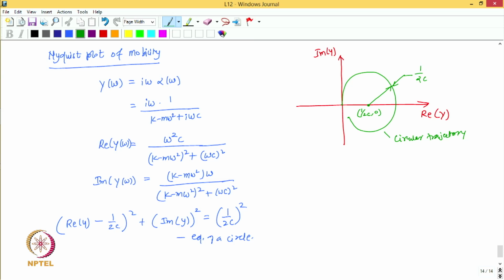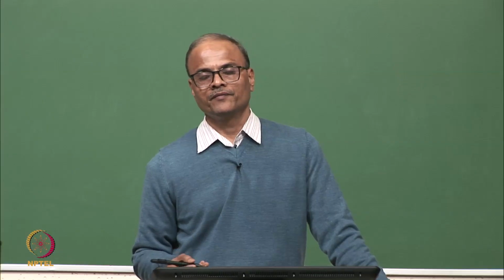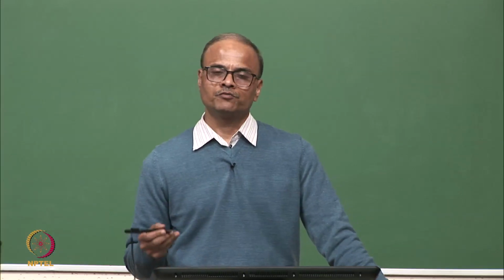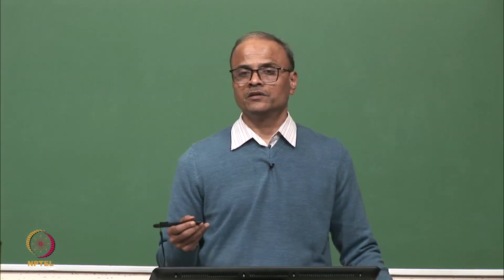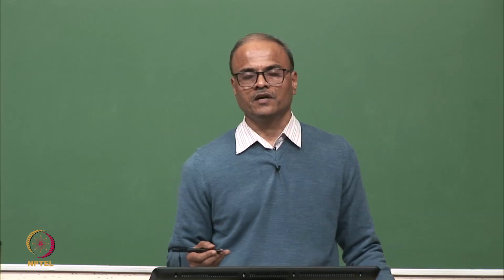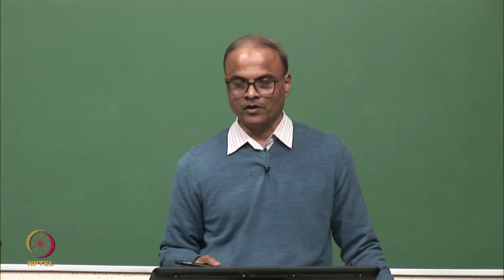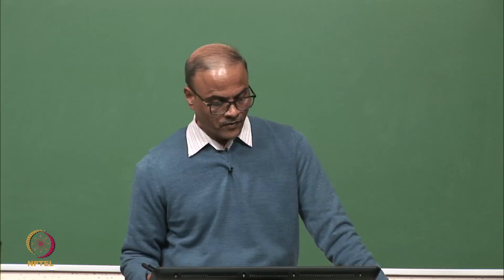This is a very important property of the Nyquist plot of mobility for a single degree of freedom system with viscous damping, and later on we will make use of this property in one of the methods of modal analysis, where we will see how this property is used to determine the modal parameters.